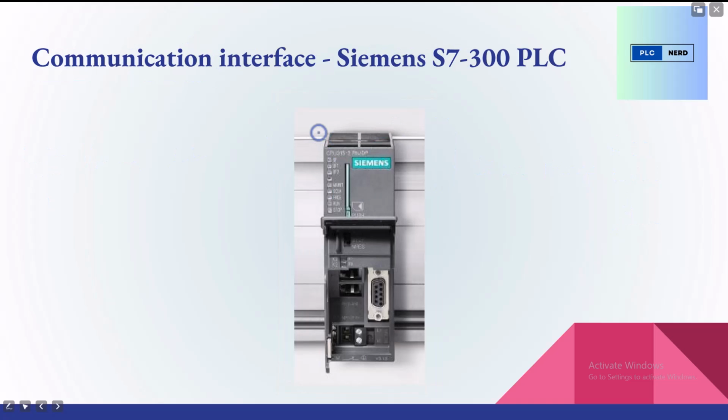We also have some communication interfaces. In this case, we have a built-in communication interface in the CPU module, and this is for serial communication. We can use it for Profibus, which uses the RS485 communication protocol. We can also use Modbus and MPI. All these are communication protocols, and this port ensures that the PLC is connected in a network. So this is the communication interface of the Siemens S7-300 PLC.